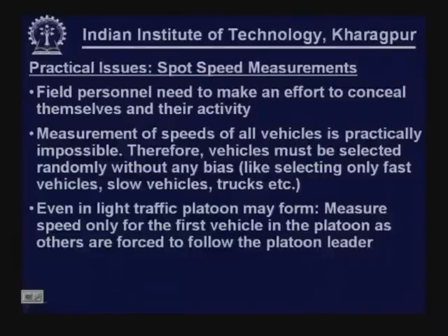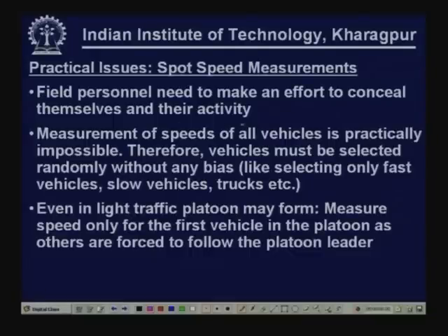Let us have a look at those points. First is, field personnel need to make an effort to conceal themselves and their activity. I am again and again highlighting these points. It is necessary, because in a volume count survey also the same thing is applicable, but here it is more important to be away from the drivers.